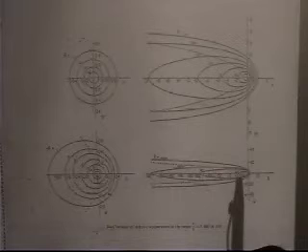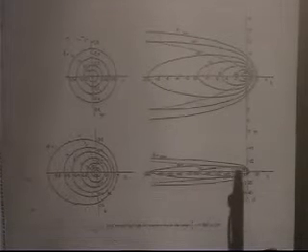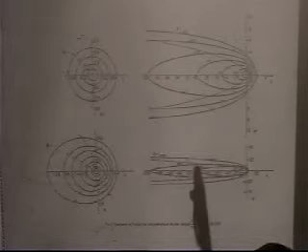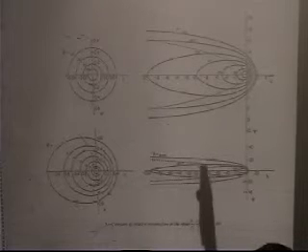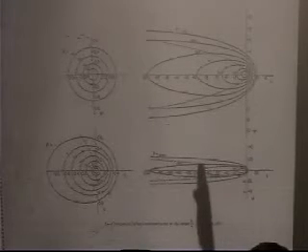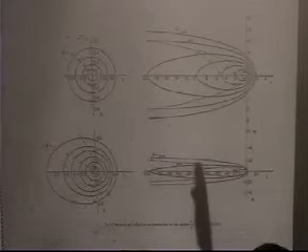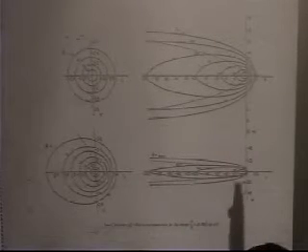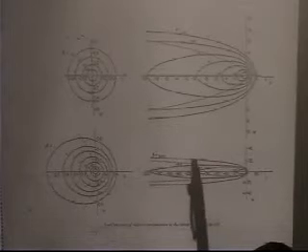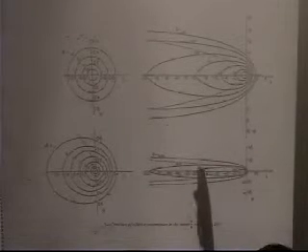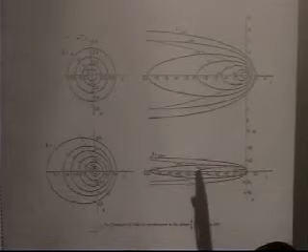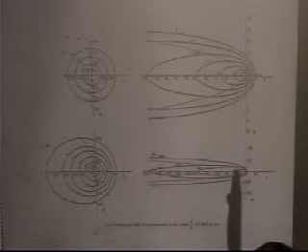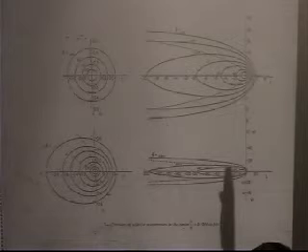If I go over here, this little circle right here, I see that if I go 2 isotherms out, I'm way over here, and this is way behind the weld pool. The maximum extent, the weld pool has already gone past. You know, the cows are out of the barn, okay? So the heat source is no longer diffusing things out. What's happening is the maximum heat approach in the y direction, plus y or minus y, is after the weld pool has passed. This is on the cooling part of the cycle.